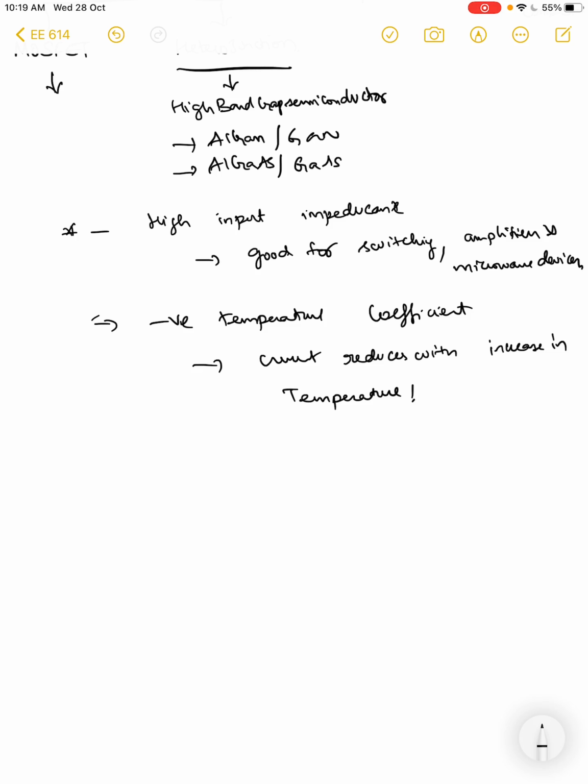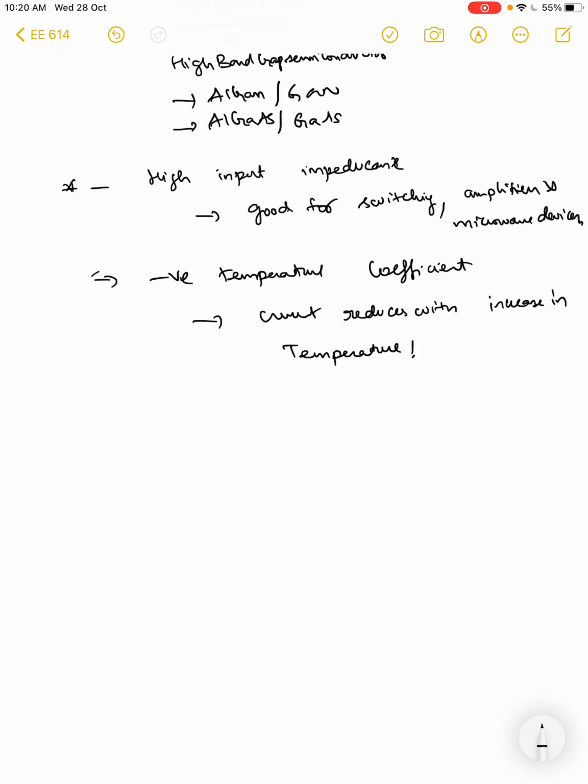You remember, we saw this situation where the base current increases as the temperature, as the reverse bias increases, right? So because the current which is causing the temperature rise is also leading to higher currents, hence you have a thermal runaway. Each feeds on itself to give you a thermal runaway. That does not happen in a MOSFET, because as the temperature increases, the current drops, which does not have this feedback loop causing thermal runaway. So it's inherently more stable than a BJT.